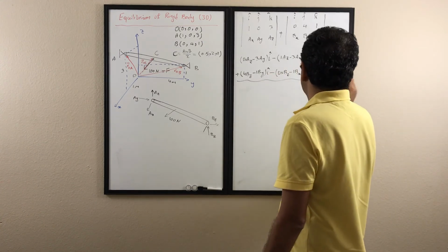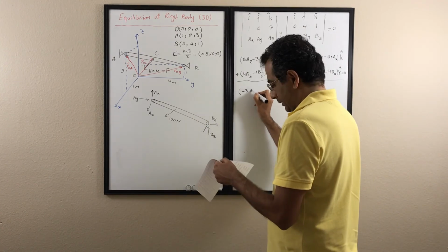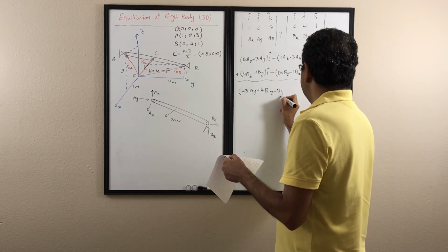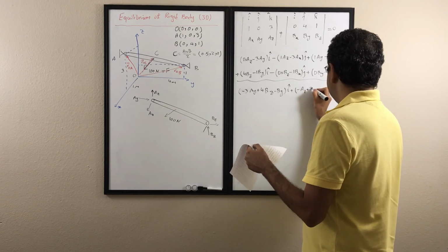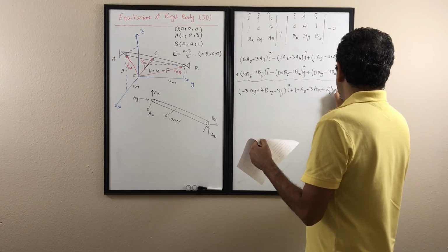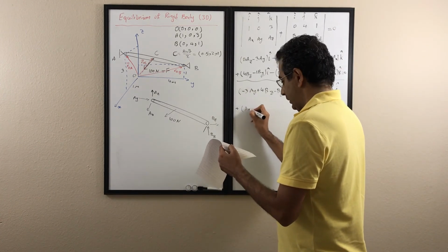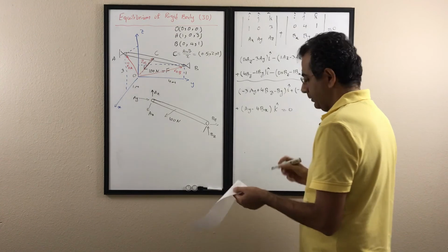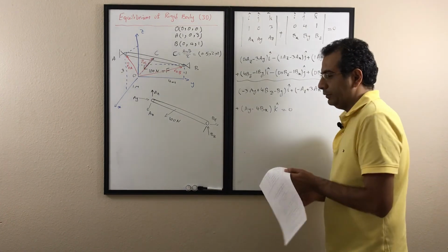So if I start from here and write all the I components together, I would have negative 3AY plus 4BZ minus BY, I, plus negative AZ plus 3AX plus BX, J, and plus AY minus 4BX, K. So basically what we have here is that the sigma M in vector format is 0.